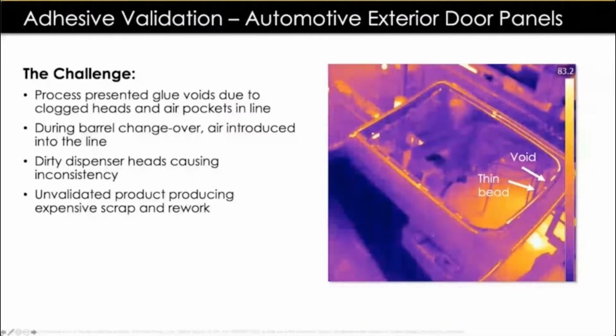So again, a validation system before we do the joining. This product was not able to be repaired in line. Though we told the robot to pull this off the line and do the inspection, that's where the operators again had to manually peel the existing multi-bond adhesive off, and replace this panel back into the manufacturing process. But again, rework time was their major return on investment issue.